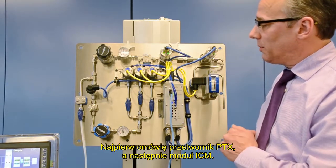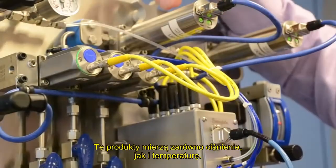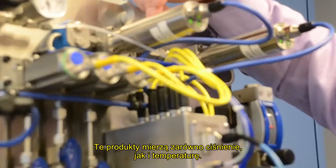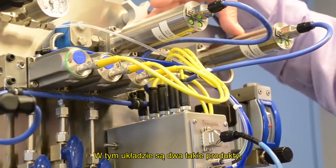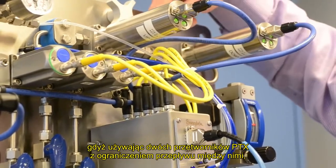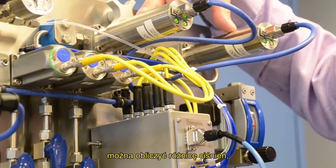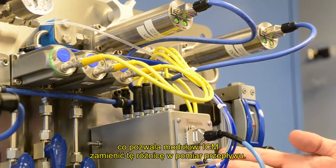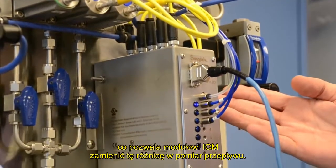I'd like to talk a little bit more about the PTX before we talk about the ICM. These products, as their name implies, measure both pressure and temperature. We have two of them in this system because by using two PTXs with the flow restriction in between, differential pressure can be measured, allowing the ICM to turn that differential pressure into an actual flow measurement.